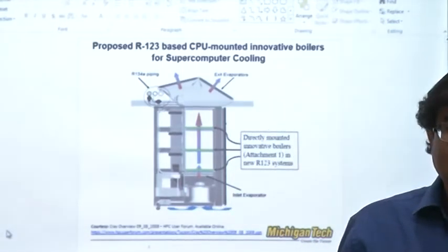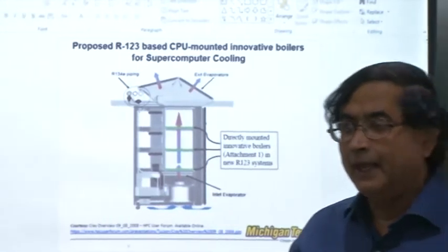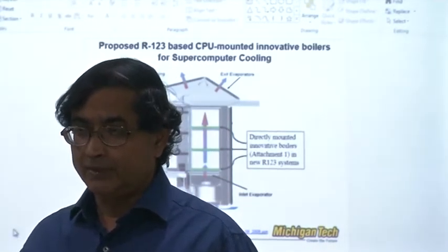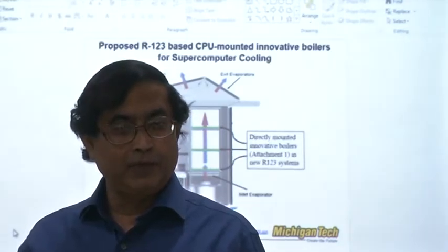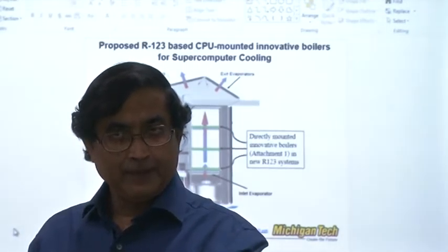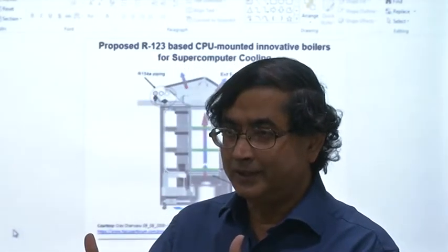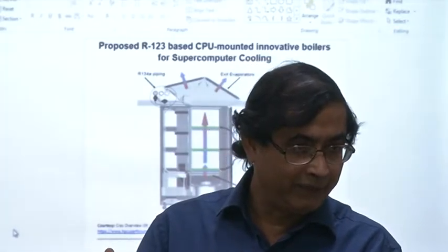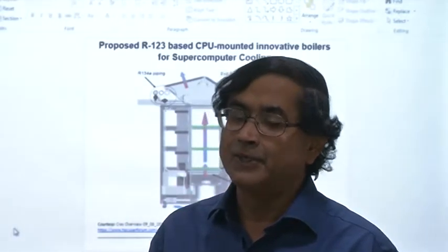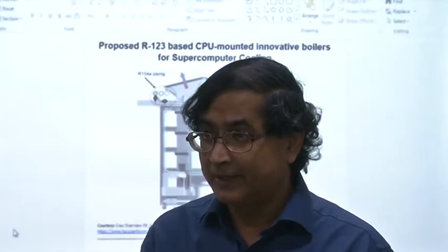I can also build my steady version of the flow regime at 50 to 100 watt per centimeter square, and then dial in the pulsations as needed and go to 500 to 1000 watt per centimeter squares. The thin liquid film would remain stable even after pulsations, but I'll have to increase the liquid flow rate, and therefore that would increase the vapor flow rate at the higher heat fluxes. So you must choose the lengths so that not only it operates at 50 watt per centimeter square, and then you go to 500 watt per centimeter square, and the vapor speed is so fast that you are getting compressibility effects. That's not right. Okay.